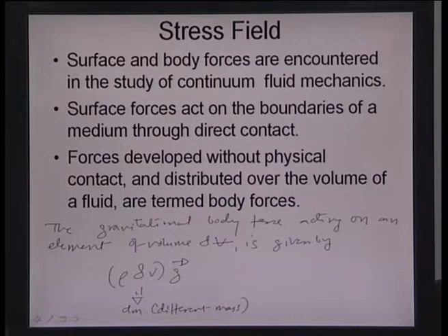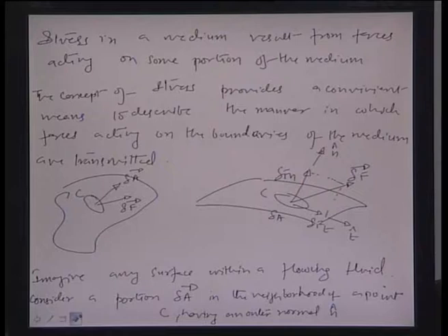So, as you can see, the body force acting on an element of volume delta V is also given by rho delta V g, and essentially this is nothing but the differential mass, rho delta V, times the acceleration due to gravity, and so it is felt within the volume.